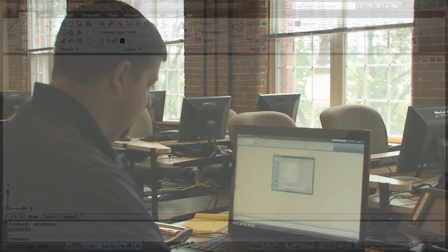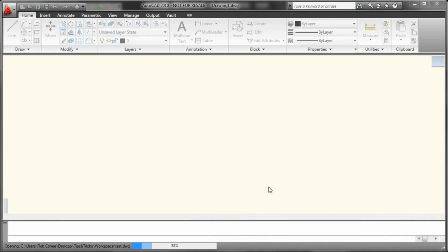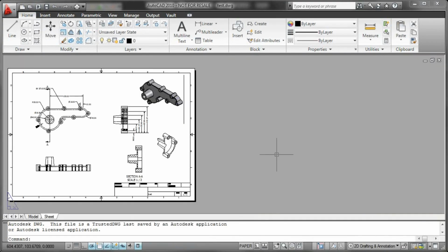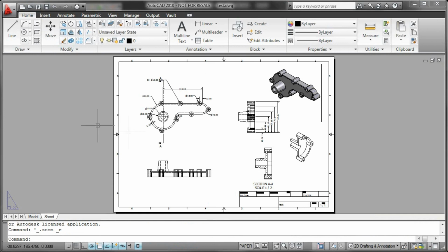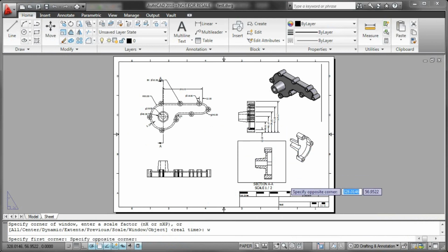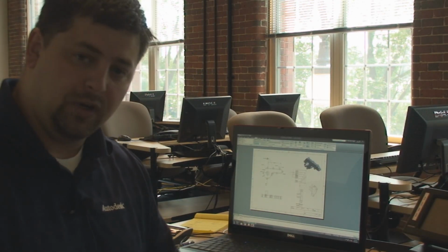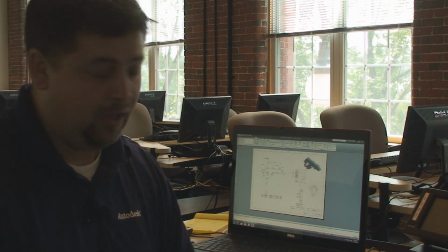They're going to go File, Open. They're going to open up the test.dwg, and it's going to tell them that it's read-only because I still have it open in Inventor, which is cool. I don't want to mess with it anyway. And just like that, they're able to use their print drivers, all of their standards. They're able to do all the things that they're used to doing with the DWG files. If I need to view, measure, print, I'm good to go. If I need to add some additional annotations of this in AutoCAD, I can absolutely do that right from here.